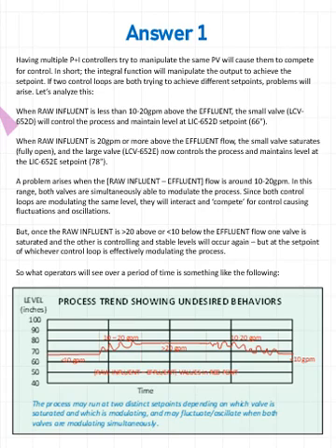So that's one issue, but another problem that arises is that in between, when both valves are modulating, when the small valve isn't fully open yet and the large valve has started to open, which in this case is about between 10 and 20 gallons a minute, both of these valves are simultaneously modulating the process, and they're trying to control the same level. Well, they're going to interact with each other.